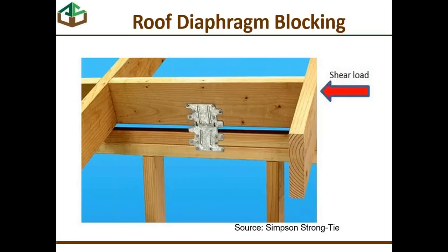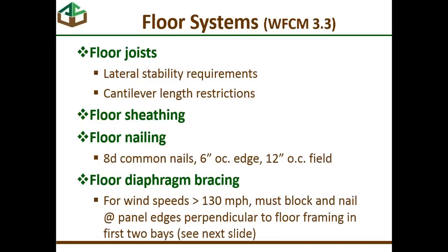So I'm not going to go into any more detail than that at the moment. It's a topic that we could probably spend a whole webinar talking about. But it is an issue that as designers and building officials we need to keep our eye on. Is that shear load adequately being taken care of at the roof-to-wall connection? Okay, let's take a look at floor systems now.